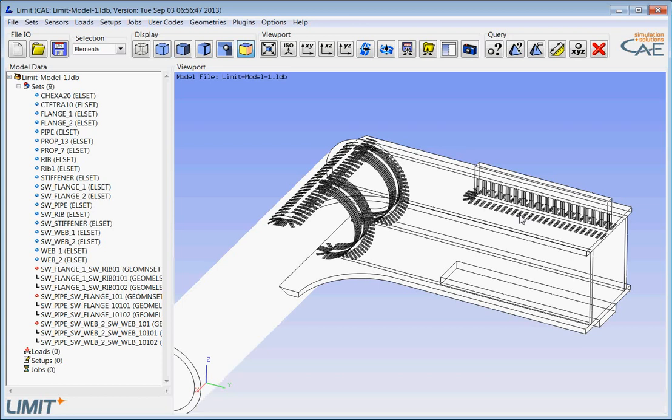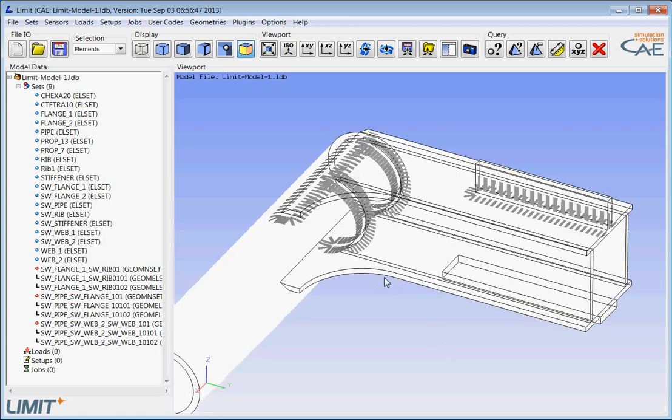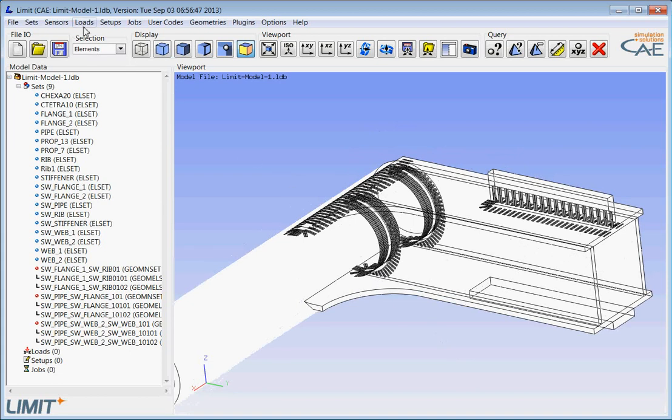And sensors actually are shells, so we get a bending moment and membrane forces, and this way we also get a linearized stress distribution over the thickness of the solid, and then we use either the average values for the nominal stress approach or the structural hotspot values for the second approach. Okay, so we have the sensors. The next step is actually to define the loads.